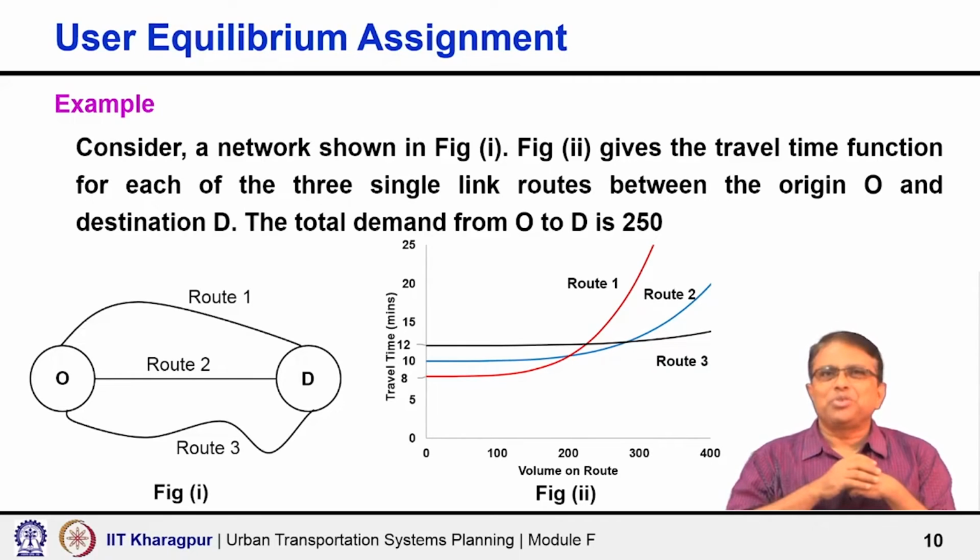In all possibility, route 1 is a low capacity route, also maybe the shortest one, whereas route 2 or route 3 may have high capacity. So, the same volume does not impact the travel time so much, and it starts increasing at a much higher volume. But then why is the zero flow or free flow travel time even higher?